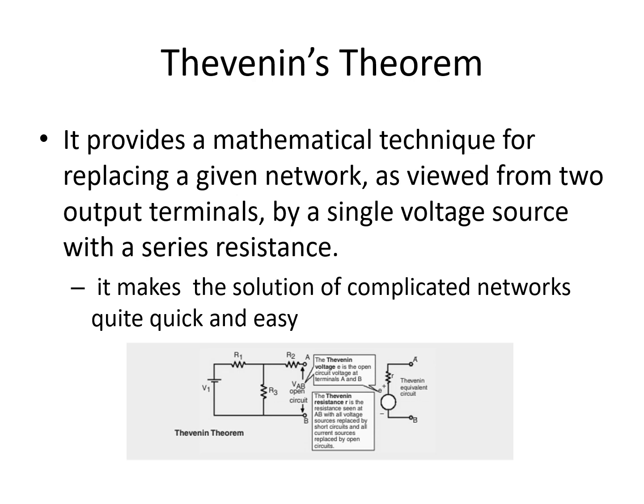For Thevenin's theorem, we will have, for example, this circuit here. This circuit is composed of a single voltage source with three resistances. If we're going to get the Thevenin's equivalent circuit at points A and B, the Thevenin voltage is the open circuit voltage at terminals A and B, so we call that Thevenin's voltage.